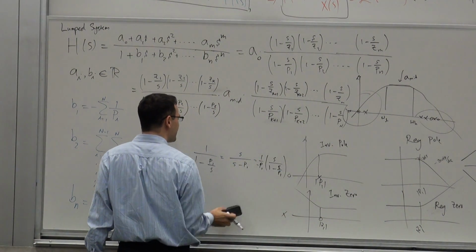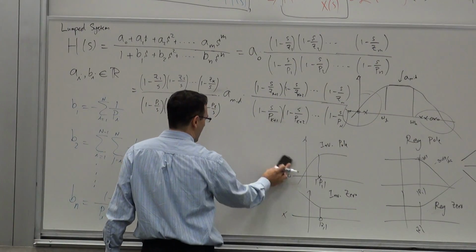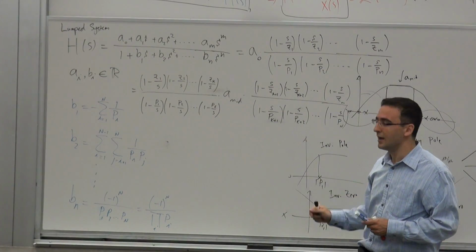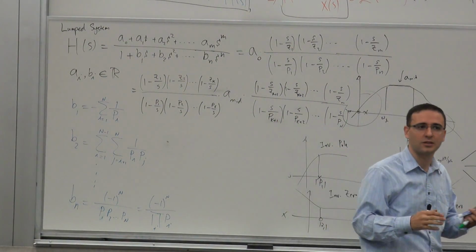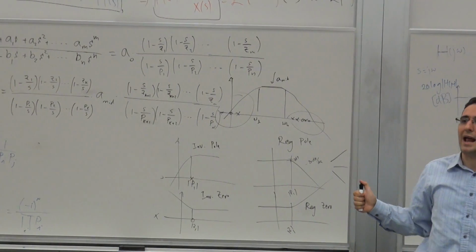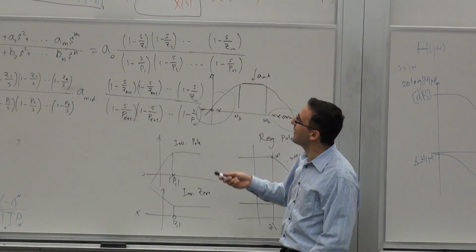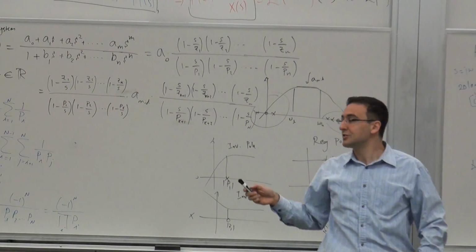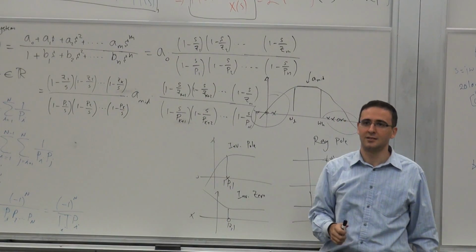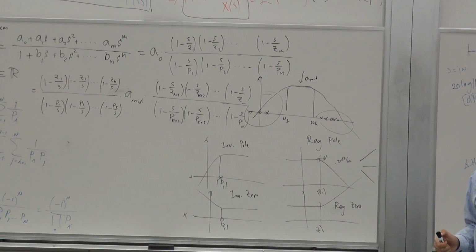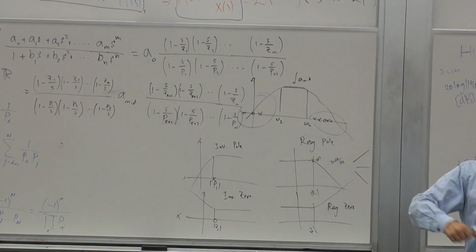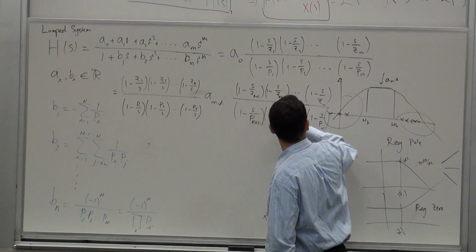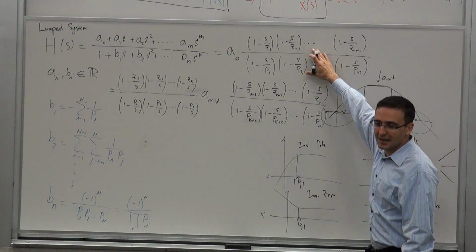As you will see later on, our techniques allow us to calculate these poles and zeros, and these poles and zeros. There are two sets of techniques we can use to determine them separately. If you're interested in this frequency only, then you don't have to write the entire thing and calculate these on the way and factor them out when you need just this. If you need that, you can just calculate that. If you need all of them, you can calculate all of them. So this is another representation which is more suited for a bandpass amplifier as opposed to a low-pass amplifier.